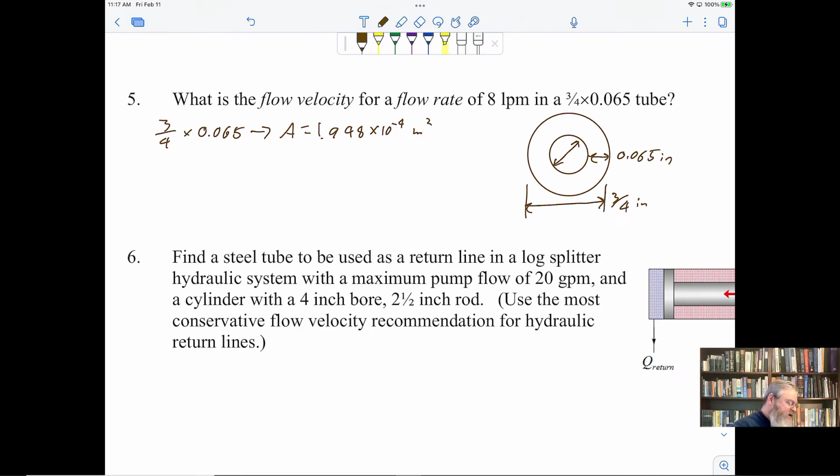and we don't actually need to look anything up. You can't do that with a pipe, because you wouldn't know what the diameters really are, because they're just nominal. Anyway, we don't have to. Also, if we did it this way, we would have an answer in US units, and we kind of wanted it in metric. And here we didn't even have to do a conversion. We just looked the number up.